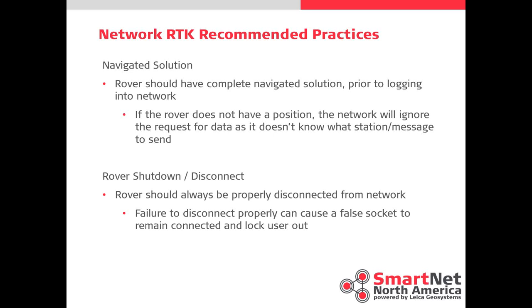Another point of emphasis we want to make sure you guys know about is rover shutdown and disconnect. Rovers should always be properly disconnected from the network, so don't just turn your rover off. Actually hit shift disconnect or whatever method you would use on your particular brand of rover to disconnect from the network. The failure to disconnect properly can cause a false socket to remain connected and actually lock you out of the network. So you want to make sure you disconnect.